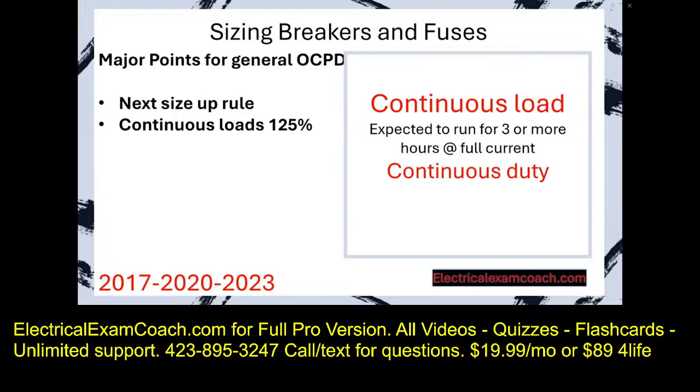If it's 3 or more, it's considered a continuous load. You may also hear the word indefinitely. Just to try to throw you off, they might use the term indefinitely. Well, it falls under the same classification of needing a 125% multiplier. Remember, it's just another demand factor.